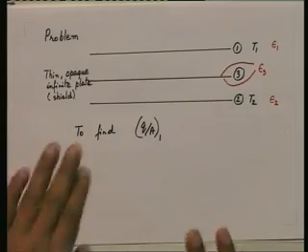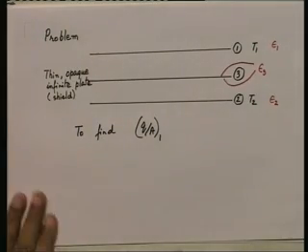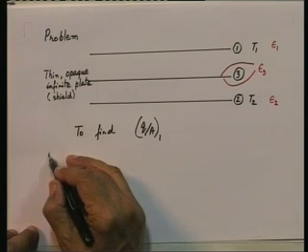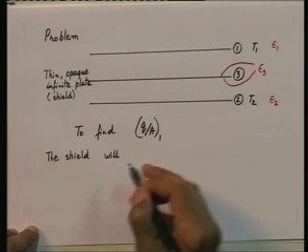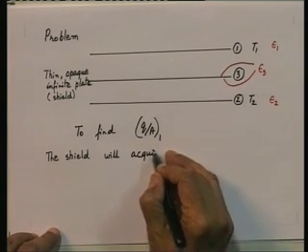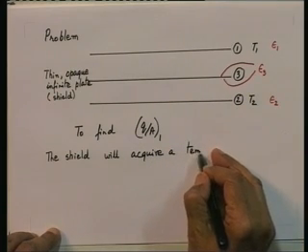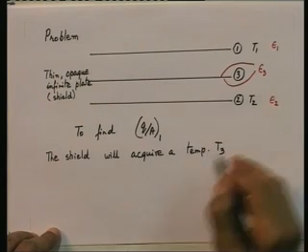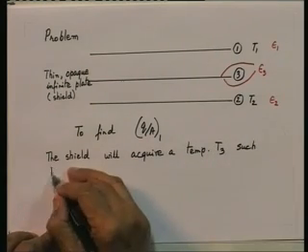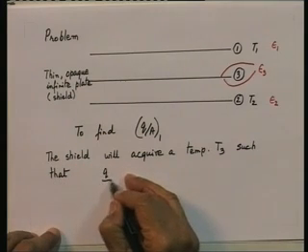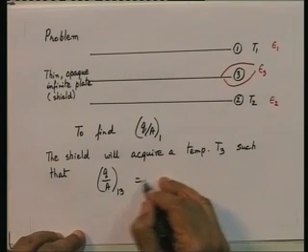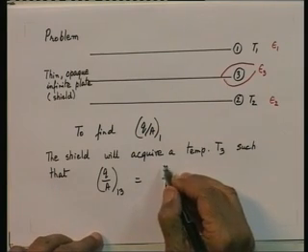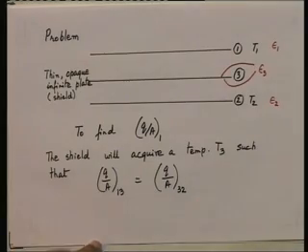It is something between 1 and 2. So, it is like a shield. Now, it is quite obvious that the shield will acquire a temperature T3, such that Q by A 1 to 3 will be equal to Q by A 3 to 2. Do you follow? That is what is going to happen in the steady state.